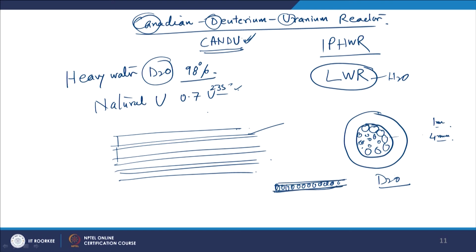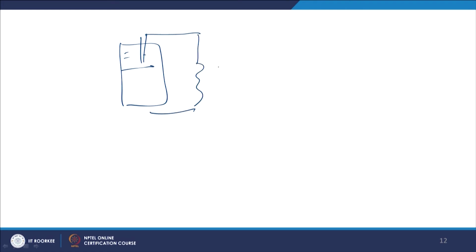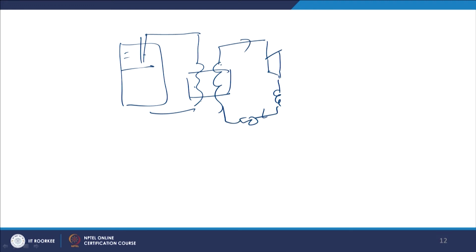Now, this steam which is generated is collected in a header. There is a steam header at the top, and from the top the steam is taken to a heat exchanger, and through the heat exchanger the heat is transmitted to the working fluid, that is H2O water, and again it goes to the turbine and condenser and then pump and again back to the heat exchanger.